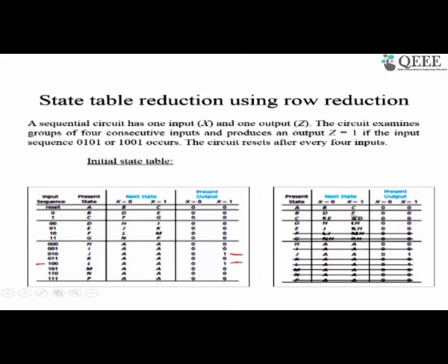Next what we do, again we look at these and see whether further reduction is possible. So here we see that these two are HH, and these two are also HH. So these can be removed, C can be removed and we can retain only D. So wherever C occurs we retain D. That is what we have done here also, and like that we have reduced further states.